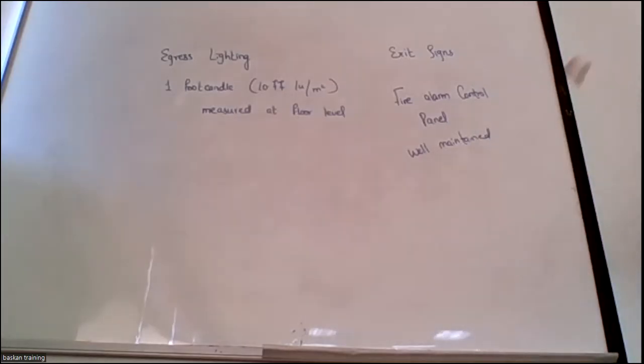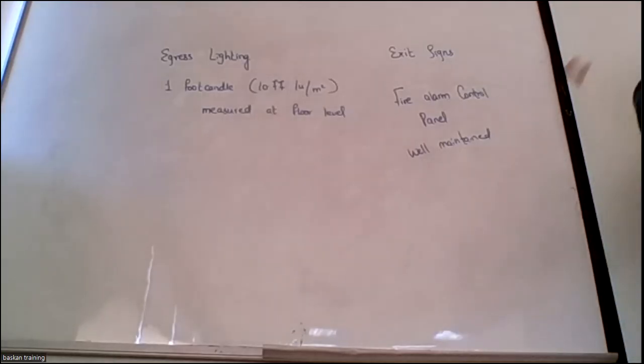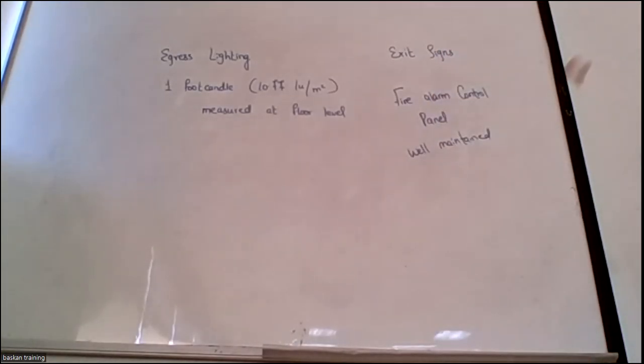People, you'll see even quite professionals, will just clean the detectors and leave. They will just check the detectors and go. They will switch off the control panel for 5-10 minutes, but they are not testing anything. You are not putting any load on it, merely LEDs. So how do you know the battery is going to perform? The first thing is that you switch off your power supply, then do all the testing on the batteries. Then you will know whether the battery is capable of carrying that load or not. Let your sounders, your flashes, your detectors be in operating condition, let it run on the batteries.